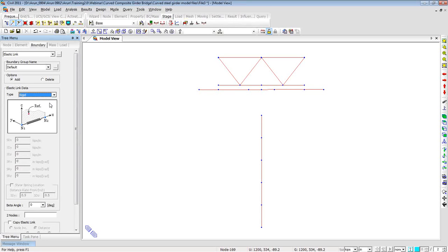Basically, whenever you want to create members with infinite stiffness, both behave in the same way. But for rigid links, you need to have a master and slave node behavior, and they cannot be applied in a sequence. Let's say if I want to have 3 links in this plane, it will be difficult for me to define as master slave, master slave, master slave, because if one node is master, it cannot be slave to another node. So there are some technical issues while defining them in series.